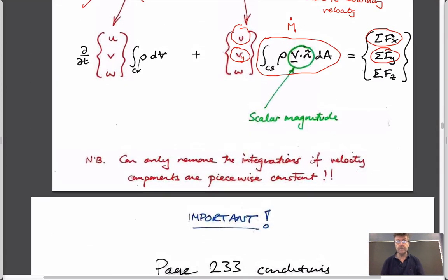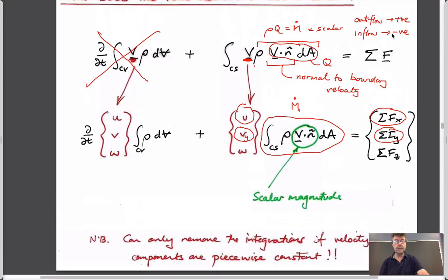And so we said before that when we deal with this, we're basically going to ignore rates of change terms in time. And so we can just use this equation on the right-hand side. And so what we see is that there's a mass flow rate here, which is multiplied through by a velocity. And so the sign convention that we'll use for the mass flow rate is exactly the same as before.